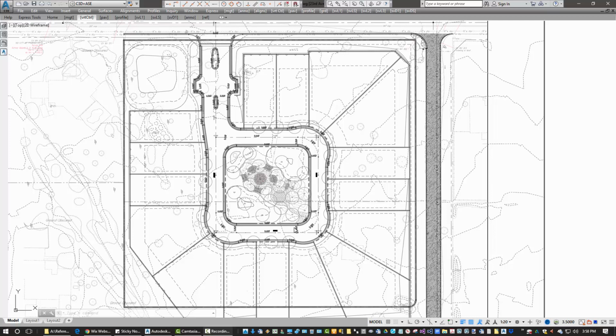After the markers and flow labels are in place, you can define specific areas where you'd like to maintain a certain elevation difference between markers, and even before you establish elevations at any of the key points, it might be a good idea to set those constraints first. So for example, let's look at this intersection.